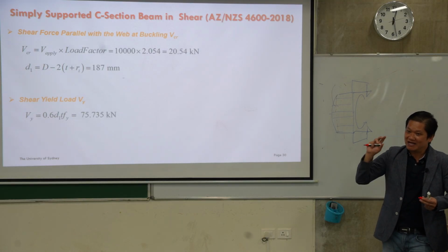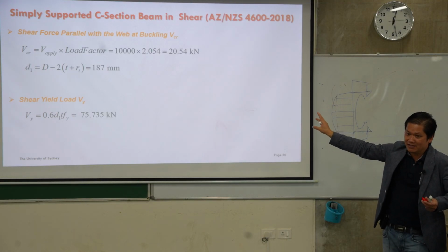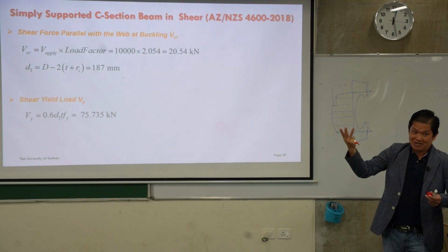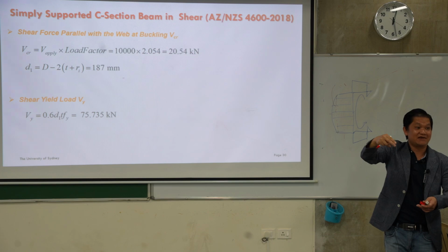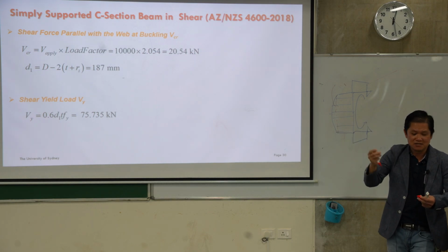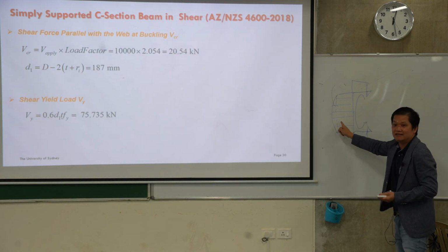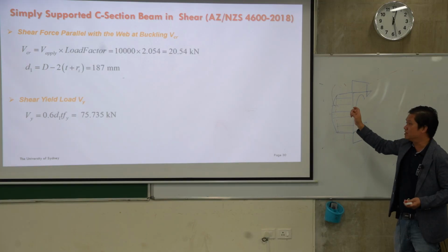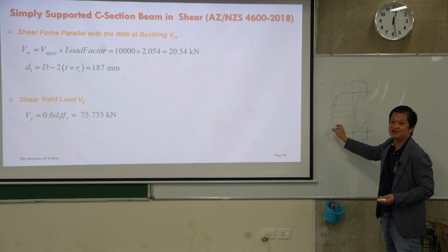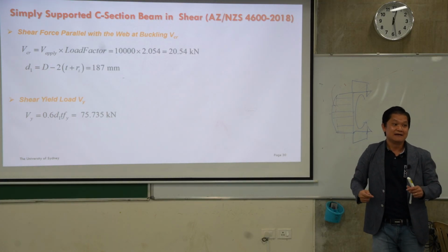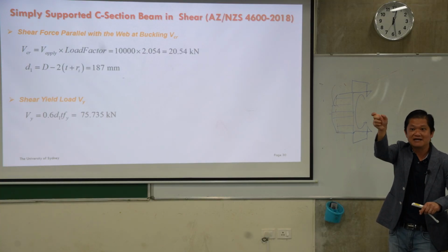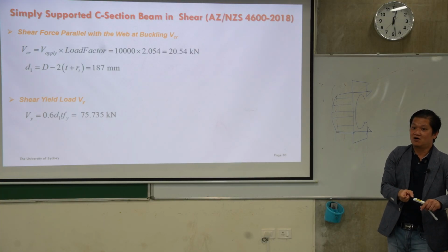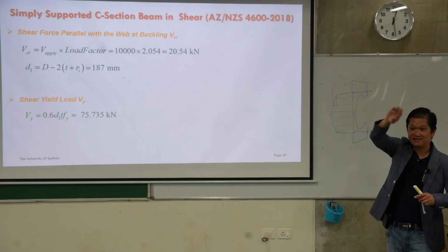So when you work out the eigenvalue here, and you work out the stress, and you back-calculate the load by the equation Kv, right? As I explained, you're using average stress, and you're using that area only, because shear stress is load divided by area of the web, not everything.